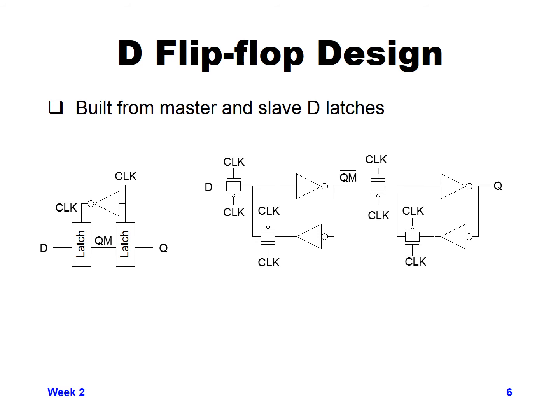We basically have 4 pass gates and 4 inverters, and since each of them has 2 transistors, we have 8 gates, 2 transistors each, 16 total transistors, which is one of the most compact designs that you can get for a D flip-flop.